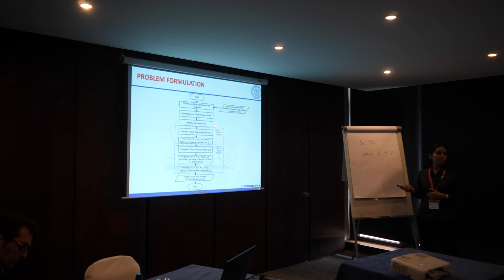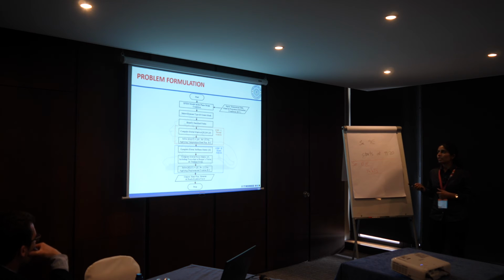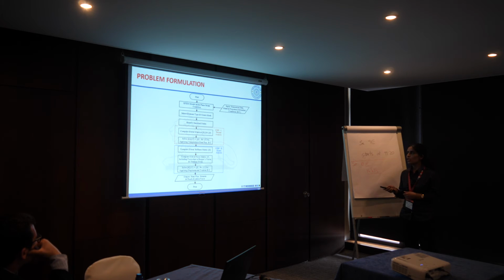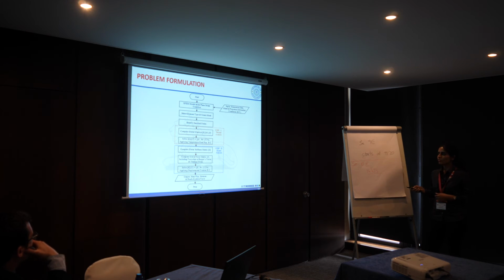First we will need some inputs. For those inputs we will need some geometrical data, material properties, and boundary conditions. All those are first defined, and then the XFEM model under plane strain condition is considered here. Then we will define some element types and create the mesh. After that, we will identify which nodes are over the glide plane and which nodes are at the dislocation core. Those nodes will be identified, and then at those nodes the enrichment functions will be defined, so that the shape function will be modified.